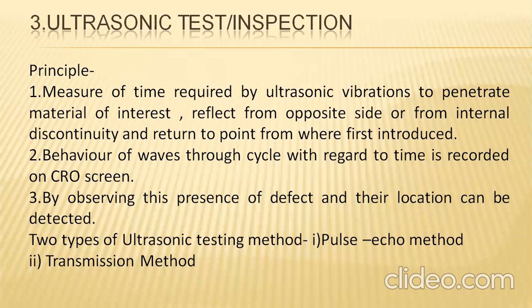But in the case of the ultrasonic testing process, there is a great advantage when compared to that process. Here, the echoes are generated at a high range of frequency, more than 20 kilohertz, up to a maximum of 20 megahertz and greater, and are utilized for identifying the maximum thickness of objects. The object which needs to be measured is placed within the fixtures.